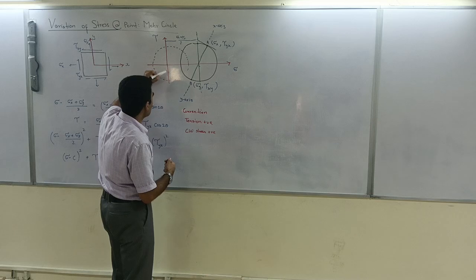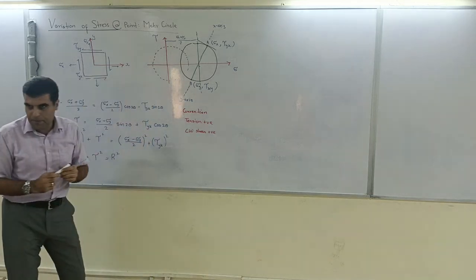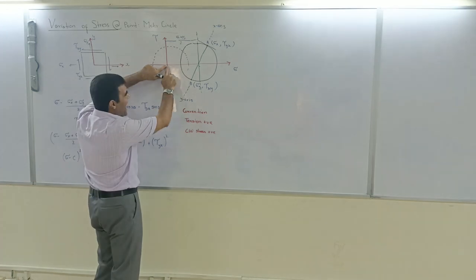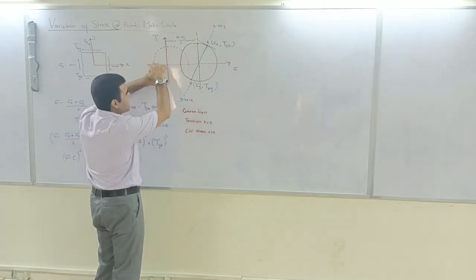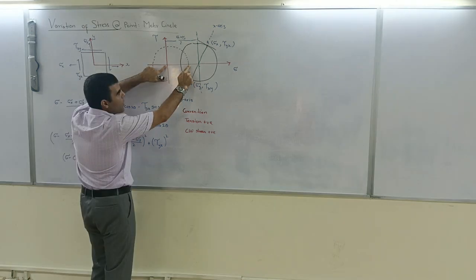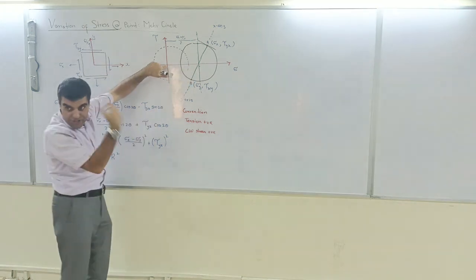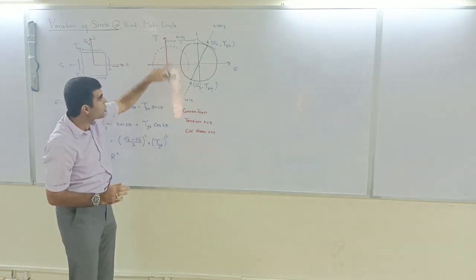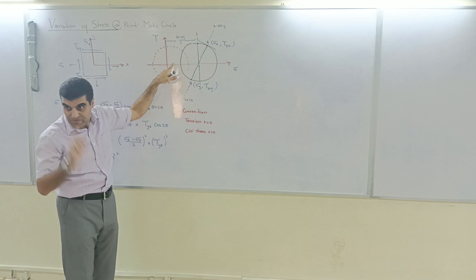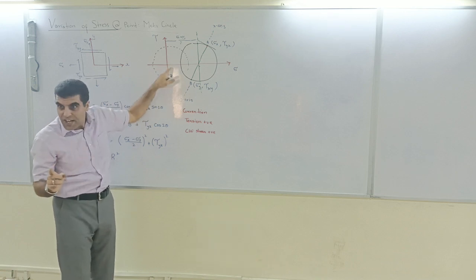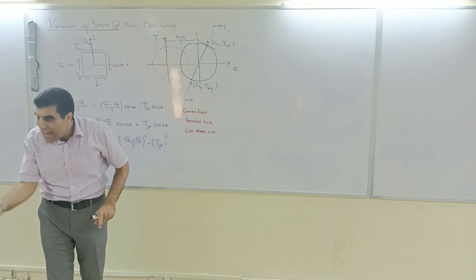If I draw my Mohr circle like this, for example, what do you have? At the principal axis, you have one positive, which means tension stress, and one negative. And they both are at 90 degrees in the Mohr circle. So in reality, they are at 45 degrees.